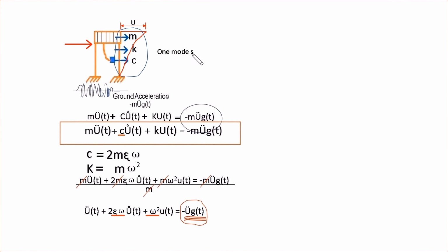Every mode shape has one natural time period. So this deflection, if we multiply it by the stiffness of the structure, we will get the shear force, which is what we need in design. And remember, the mass of our structure is known, because when we design, of course, it already has sizes, so we can get the mass. So if we divide the shear force by the mass, then we will get the acceleration.